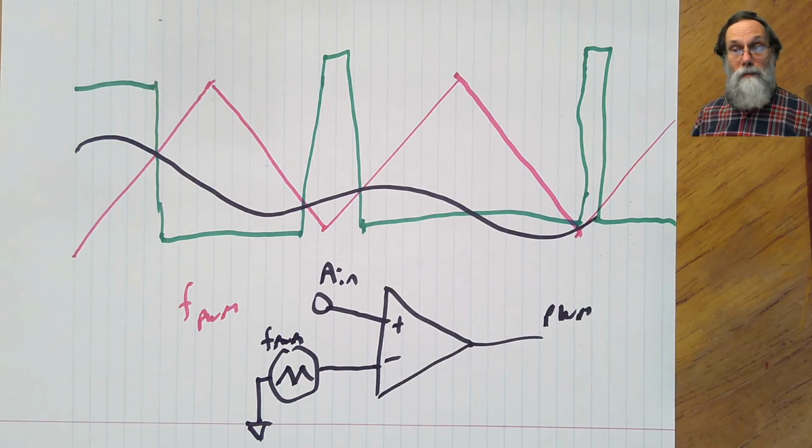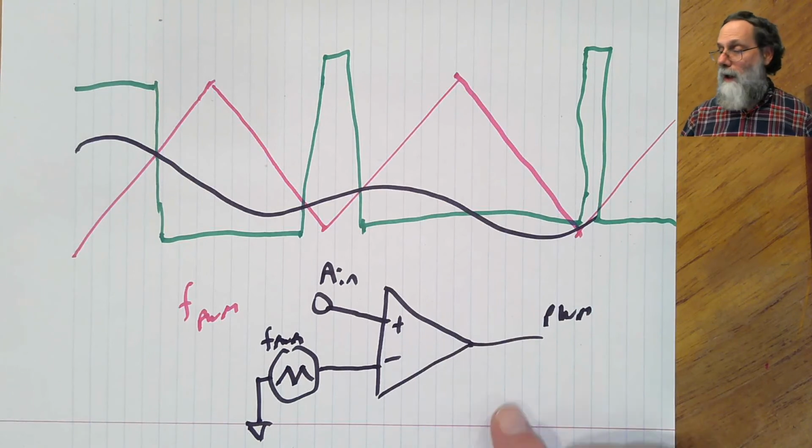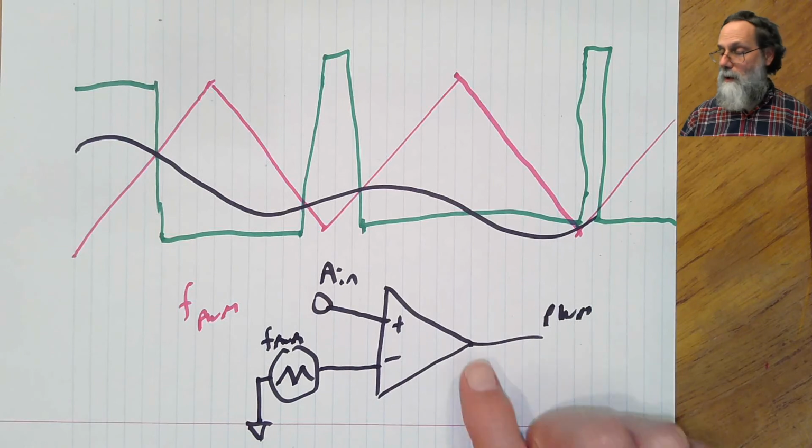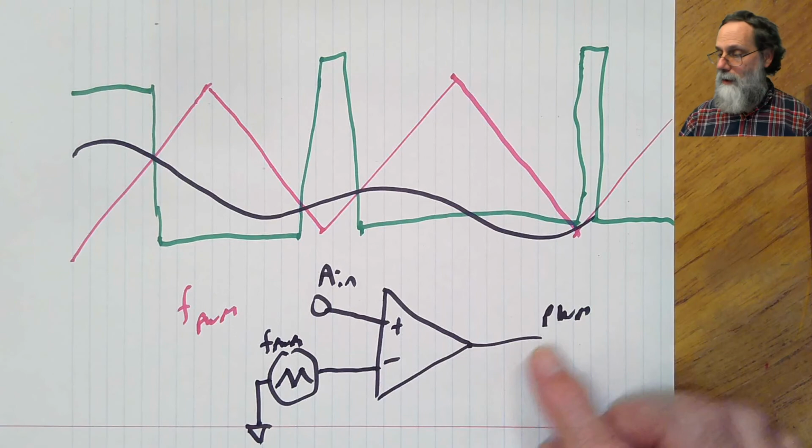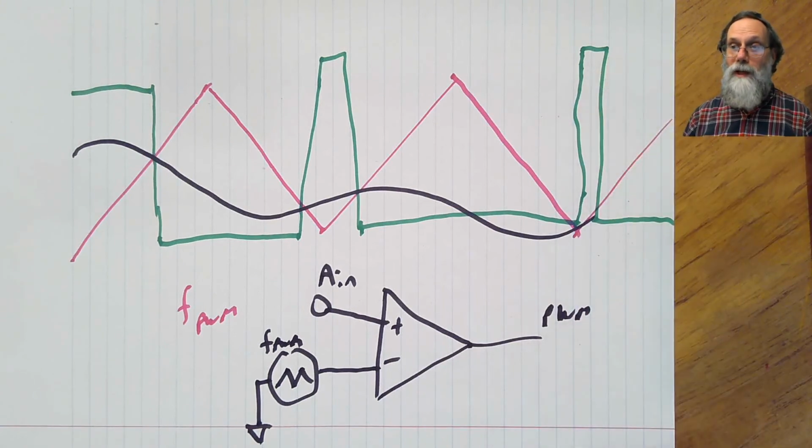And that's really all there is to generating a PWM signal. We'll look in subsequent videos about how we can take this PWM signal and convert it into a large PWM signal to drive the loudspeakers, because what comes out of a comparator here is only a very small current. So we get a nice digital signal in terms of the voltage range, but small currents, so we can't drive anything like a loudspeaker with it. That's about it for generating PWM signals.